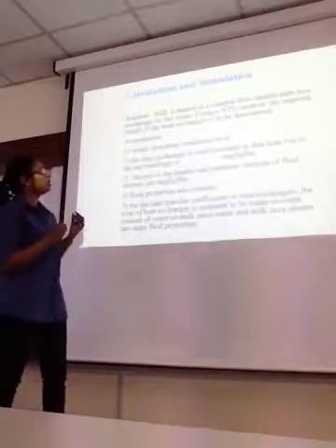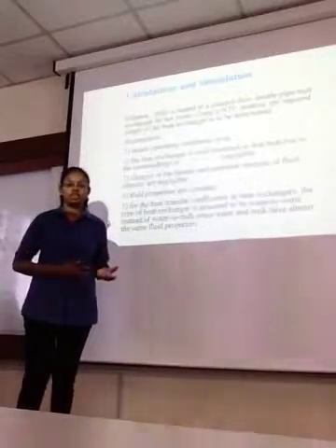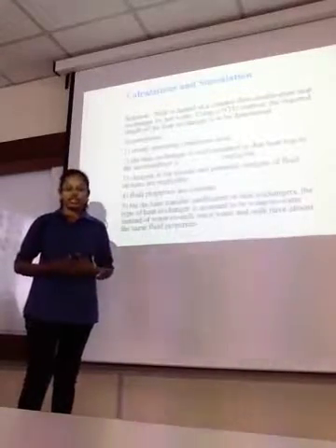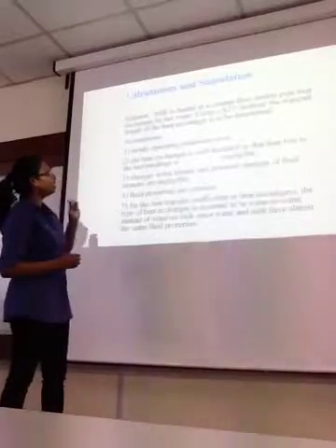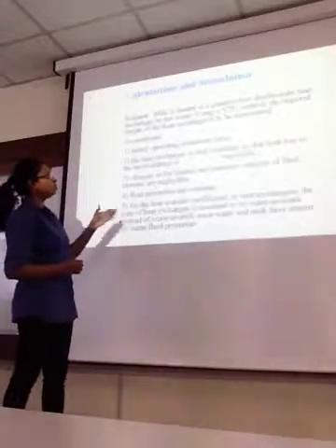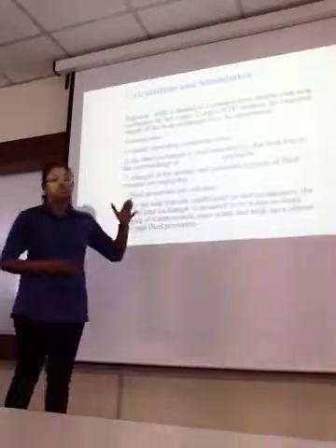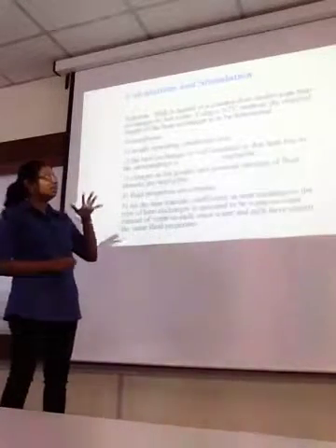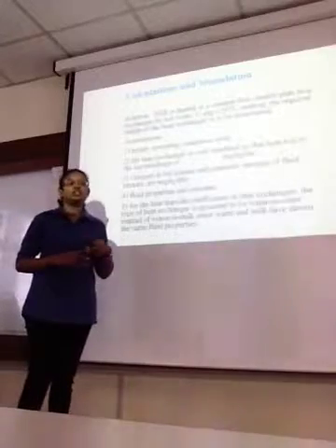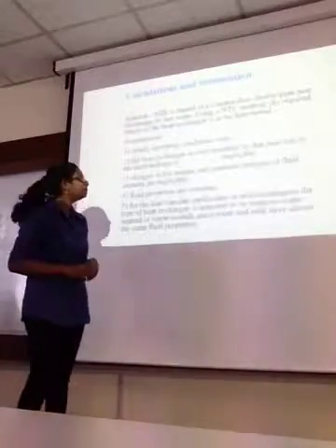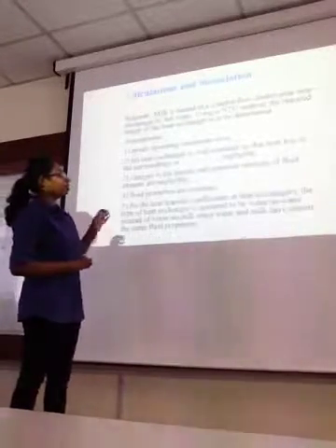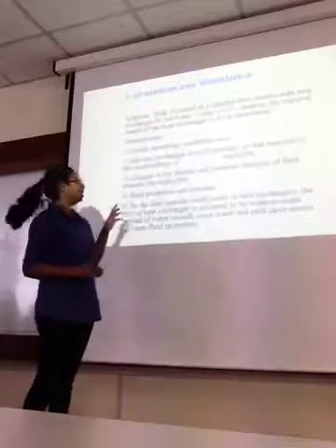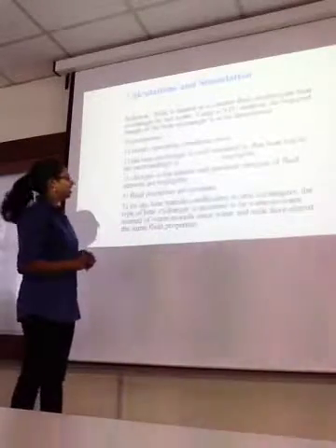Actually, in doing this heat exchanger, we use the NTU method. What we assume is that the steady operation condition must exist, and the heat exchanger must be well insulated, so heat loss to the surrounding is negligible, and the kinetic and potential energy of the fluid streams are negligible.